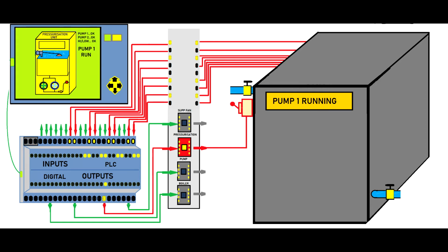You will set up the pressurization unit for a maximum quantity of water to push into the system. Otherwise, if you have a broken pipe, you will flood the store, and that will be pretty unpleasant for you and for the customer. So just make sure that you have a reasonable quantity of water, and do not try to put too much. Once the pressure reaches the value that is set up on the pressurization unit, the pump will stop. Until here, everything is okay.